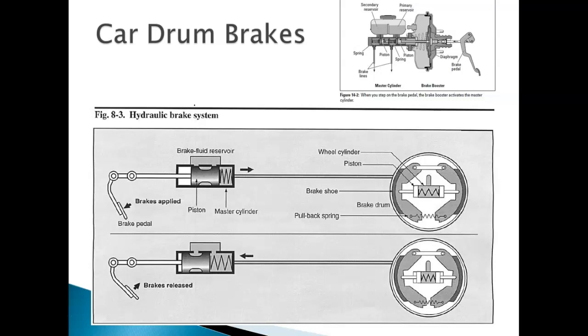You never ever want air in your brakes. Why? Because air is compressible, brake fluid is not. What do I mean by that? How many of you have ever done a belly flop? Is fluid compressible? No. Physics say no. You hit that water hard enough, it will knock the air out of you. Fluid is non-compressible. Air is very compressible. Okay?